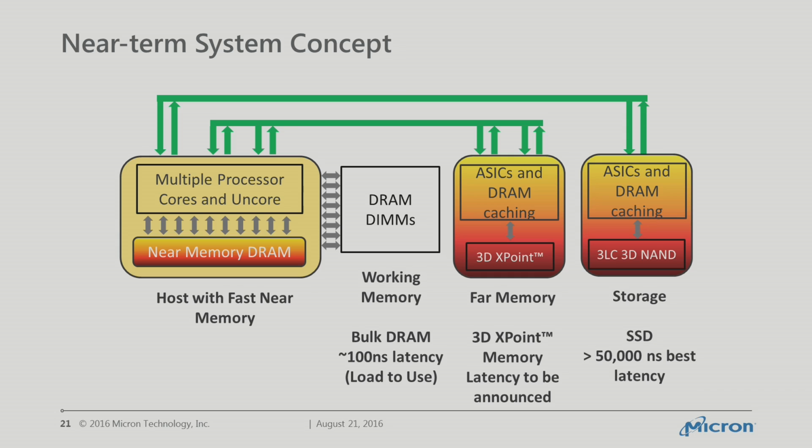50 microseconds would be if you get lucky on the ECC and you're using a 1 bit per cell NAND. A 3 bit per cell NAND cannot do that, right? So my slide is a little bit funny that way. It's maybe telling a slight fib. Well, I did say greater than, so I appreciate that. Greater than actually means a lot greater than in that case.